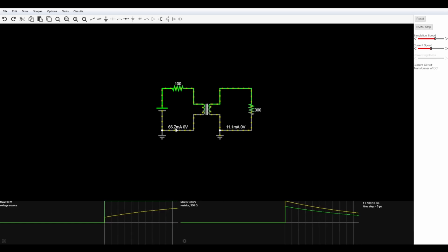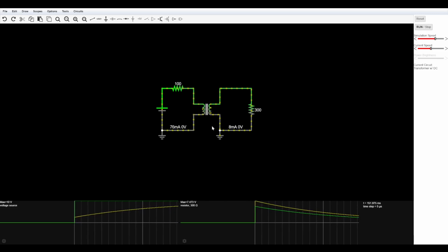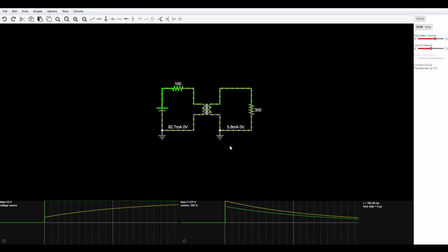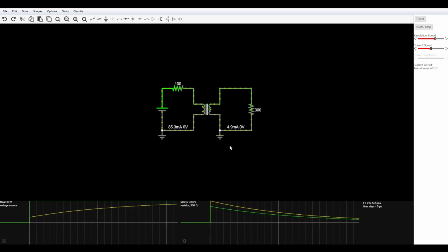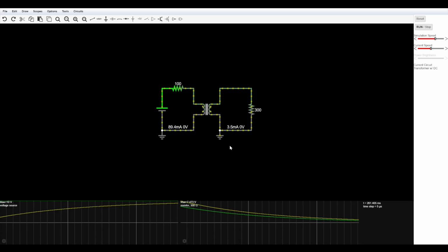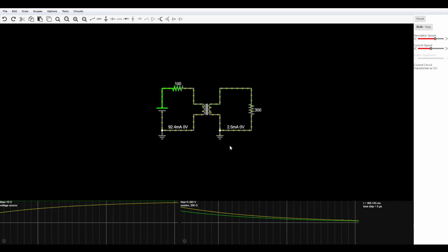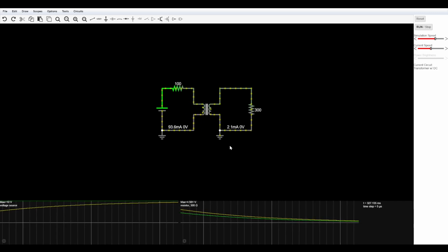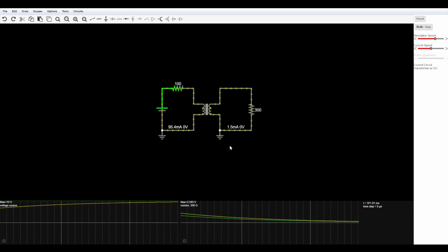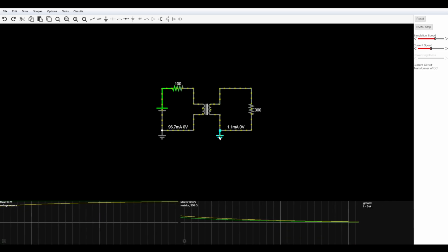Now you'll notice the milliamps is going steadily up here on the left, steadily down on the right. So the current is building up back through the battery. It's just going to keep building up, generating more heat. Eventually, in real life, the battery would probably explode or at least otherwise fail. So this is why you don't use a transformer with DC. Well, at least without an interrupter.